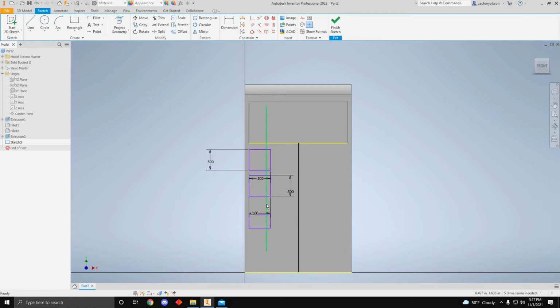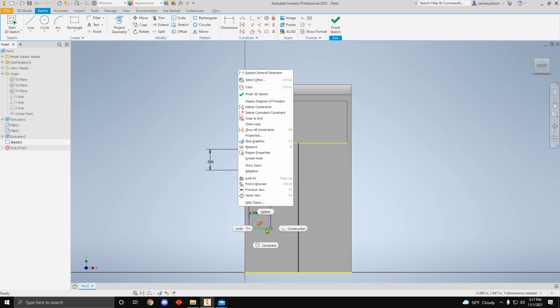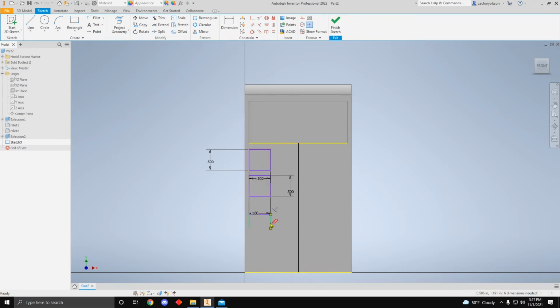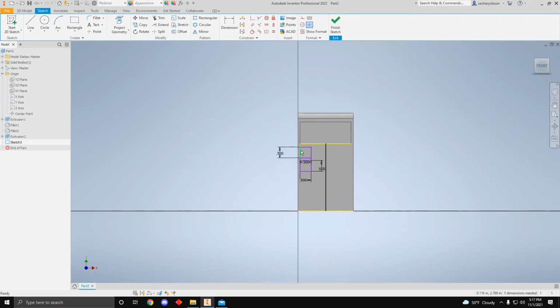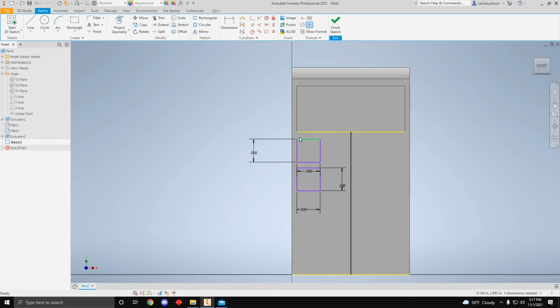Okay, and the other thing we can do is select this line without the dimension, right click, and click delete. Why are we deleting? You'll see in a second. So we're going to delete this, and zoom in, make sure we don't grab the dimension, delete that, and instead of making a 3rd button just out of randomness, we're going to go up here and grab this copy tool.